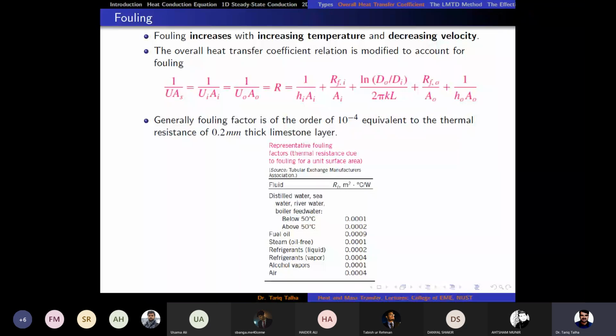That's why we need to clean those pipes using chemical treatment, because we want to reduce fouling so that the heat transfer would be more effective, because the sole purpose of any heat exchanger is to have maximized heat transfer between two fluids, right? So we need to do periodic maintenance of those pipes by chemical treatment to reduce fouling. That is what people usually do in the industry for boilers and condensers.